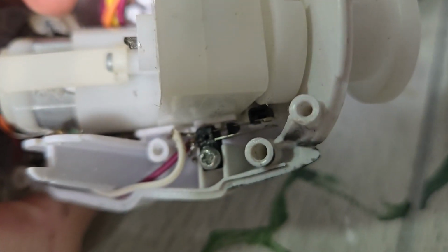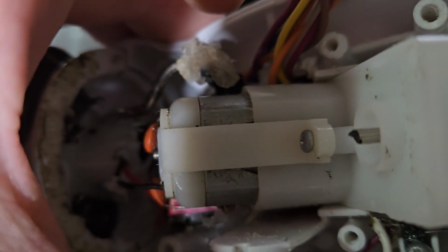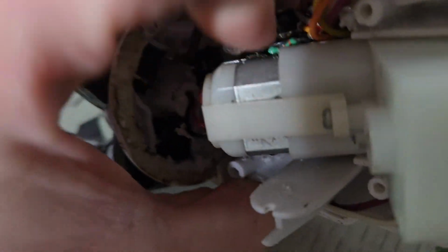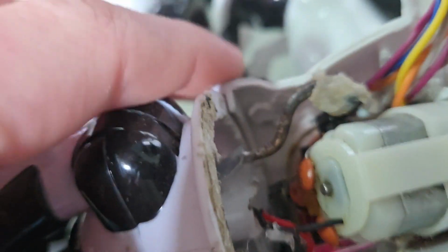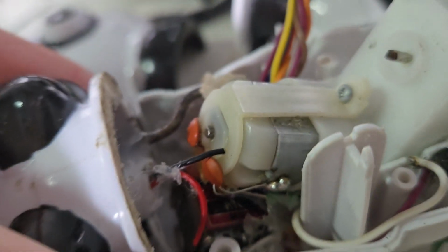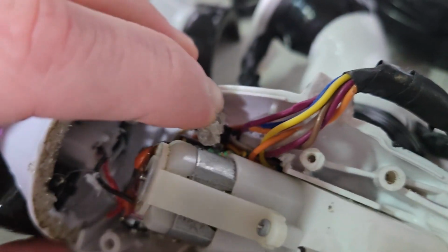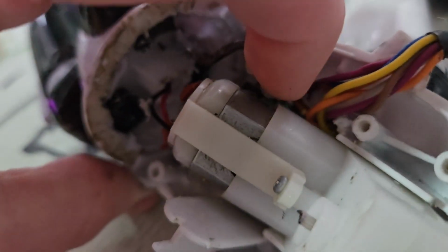You'll find that everything has been rewired, and the original board that everything went to has been removed, and the front of the claw right here has had a lot of structure removed, so we could fit a servo in here, and the bottom of the servo has been removed and it's adhered to the gearbox. And then you've got a servo arm over here with copious amounts of adhesive going to this metal rod that is embedded into the Robosapien claw.